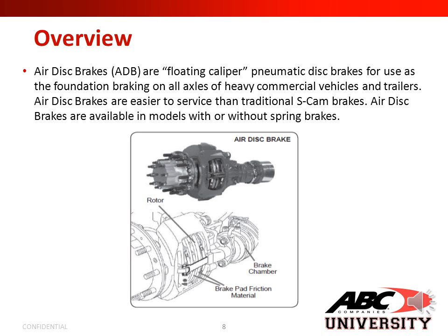Air disc brakes, or ADB, are floating calipers, pneumatic disc brakes for use as the foundation braking on all axles of heavy commercial vehicles and trailers. Air disc brakes are easier to service than traditional S-cam brakes. Air disc brakes are available in models with or without spring brakes.